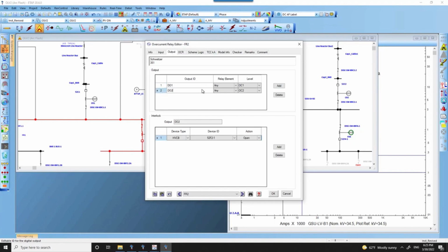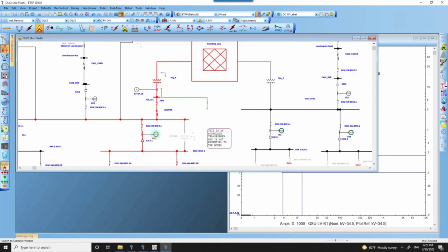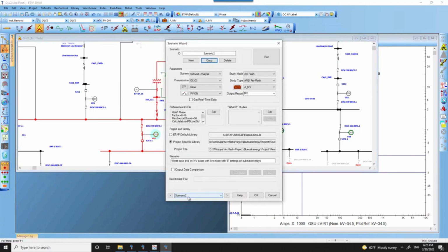multi-function outputs from the same relay were one used for the short circuit coordination to avoid any potential selectivity issues. However, for Arcflash, using the instantaneous setting gave us the correct expected incident energy to be way less than the actual calculated value. So in this case, we did have the PV arrays on, which seemed to be the worst case, where all the contribution of the sources were included.